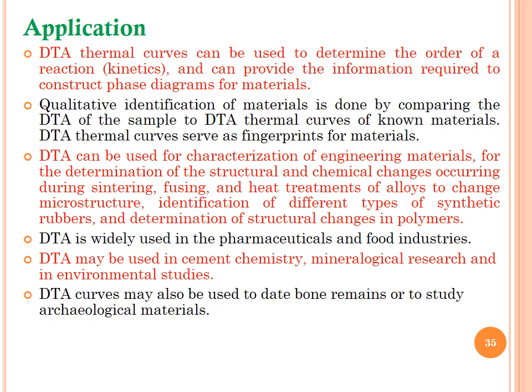So these DTA thermal curves can be used to determine the order of reaction, the kinetic studies, the physical phenomena, and the kinetics with which reactions take place between different molecules and compounds, and provide the information required to construct a phase diagram for the material. As we already discussed the phase diagram in the TGA lecture.